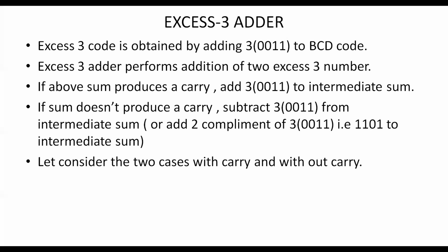That is, the XS3 adder will perform the addition of 2 XS3 numbers. If the XS3 addition produces a carry, we need to add a correction of 3 to the intermediate sum.